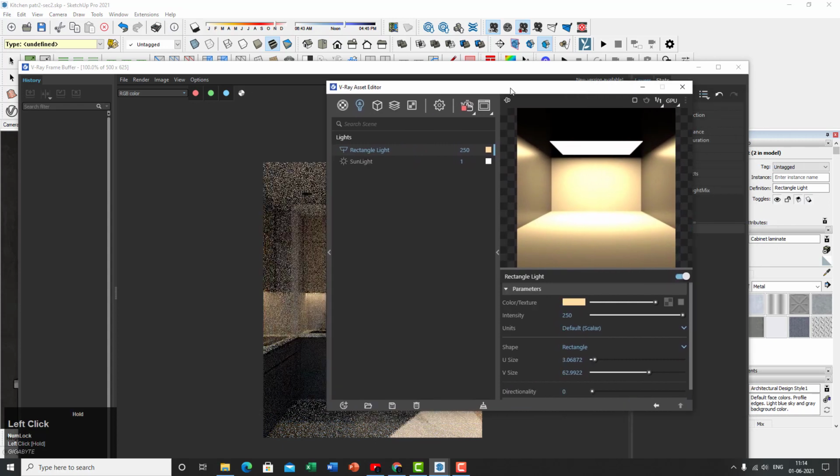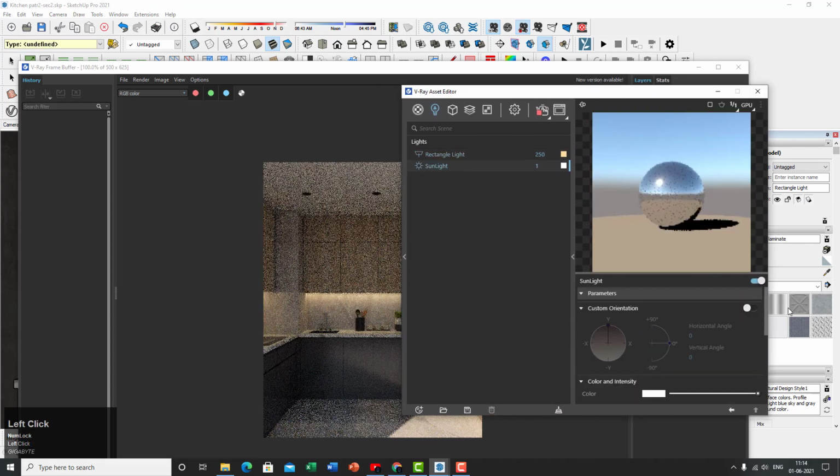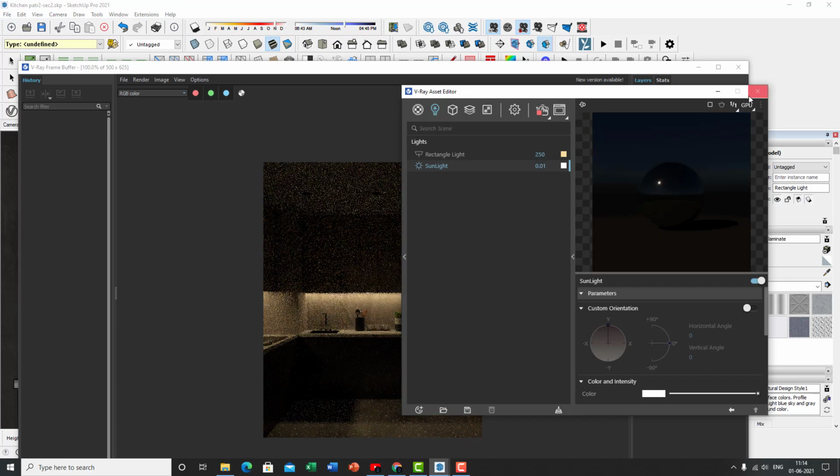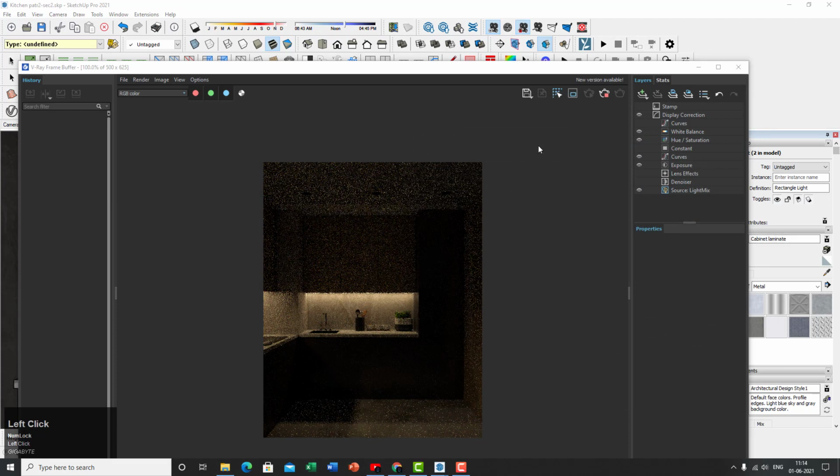Okay, anyway, we'll get back to that eventually in the end. So let's take care of the sunlight. So if you switch off the sunlight, what happens? You cannot just switch off the entire environment, because there is an environment outside. All you can do is reduce the environment light value. So the sunlight value, put it as 0.01 for the moment, and the entire room goes dark. So let's start putting on the other lights, and the room should be lit up with the help of the other lights.